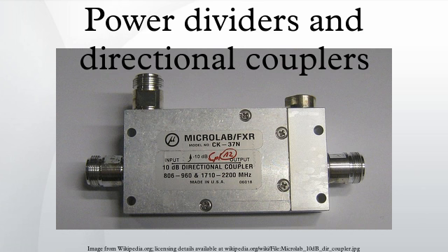Hybrid ring coupler. The hybrid ring coupler, also called the rat race coupler, is a 4-port 3 dB directional coupler consisting of a 3λ/2 ring of transmission line with 4 lines at the intervals shown in Figure 12. Power input at port 1 splits and travels both ways round the ring. At ports 2 and 3 the signal arrives in phase and adds, whereas at port 4 it is out of phase and cancels. Ports 2 and 3 are in phase with each other, hence this is an example of a 0° hybrid. Figure 12 shows a planar implementation, but this design can also be implemented in coax or waveguide.